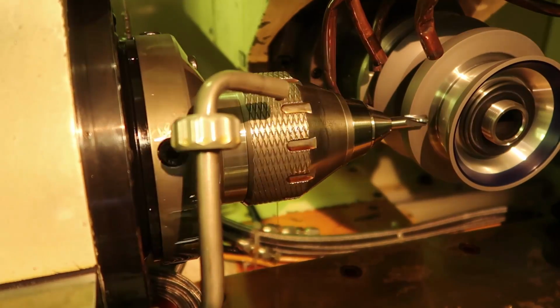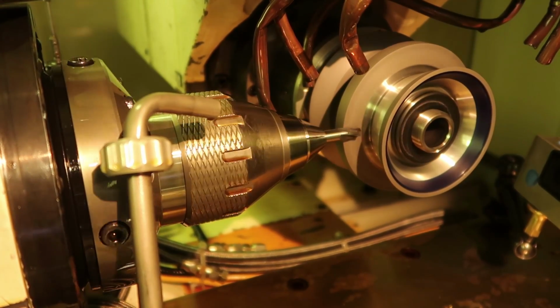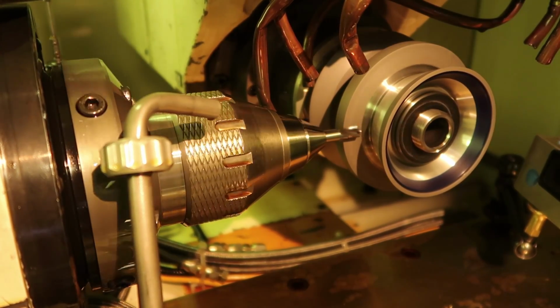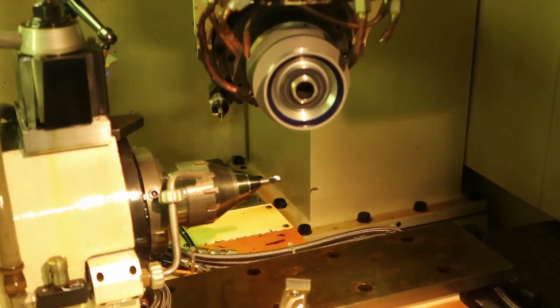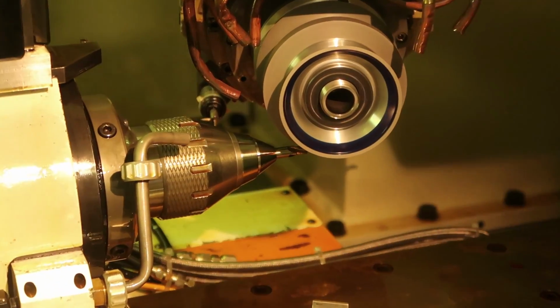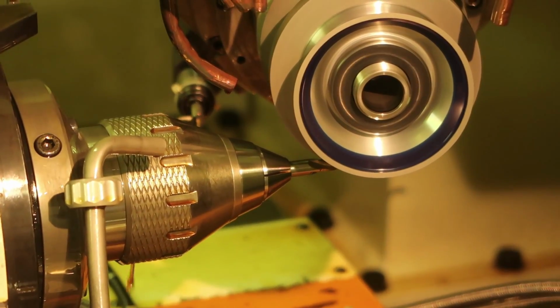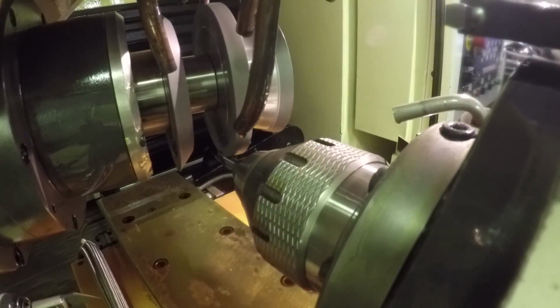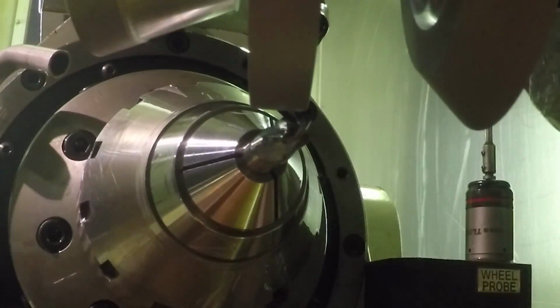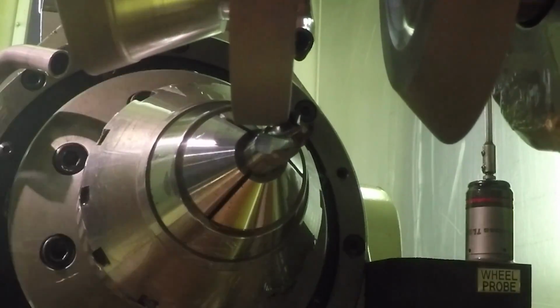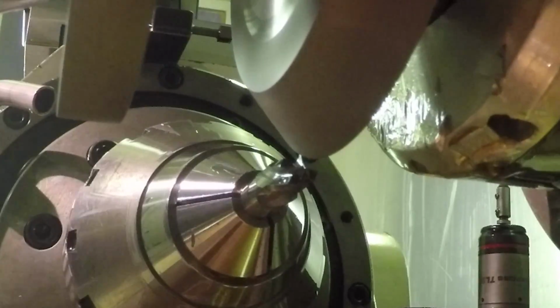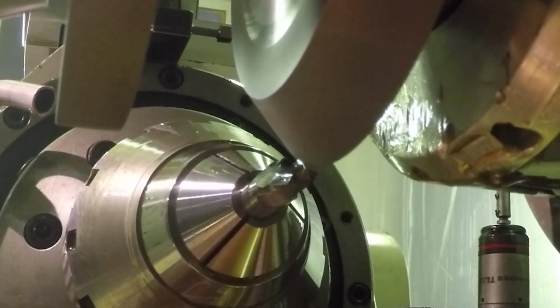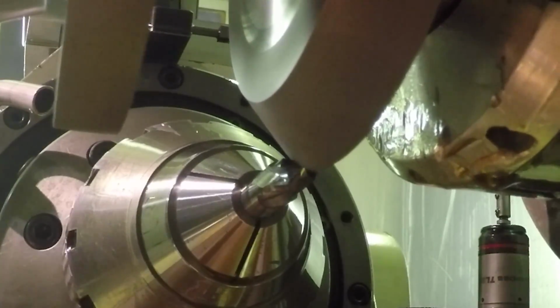Then I added this cut to take some load off the cup wheel, grinding the clearance angles on the OD. So that you didn't see in the programming, but I added it later. Here's the fluting cuts. Cutting the flutes, each one of the 4 flutes down the OD. A couple of different views of it. Then the gashing of the tip of the tool, the gashing wheel.